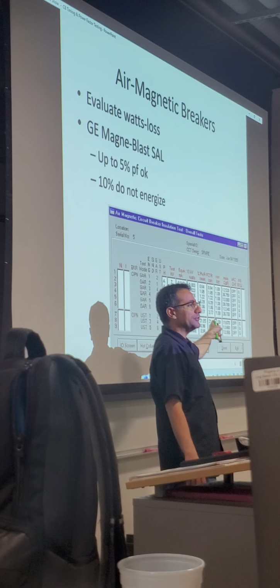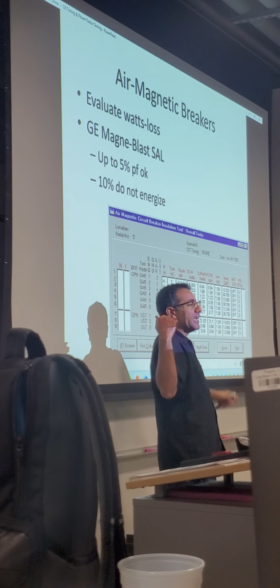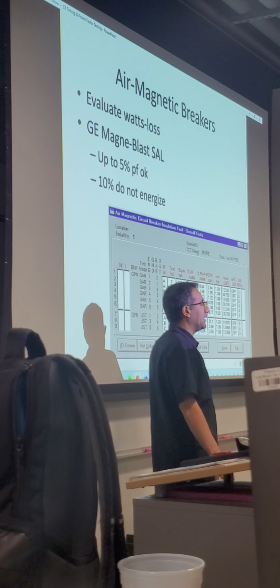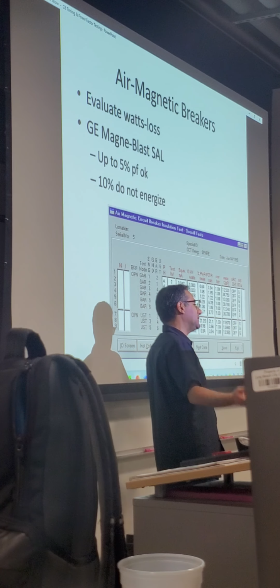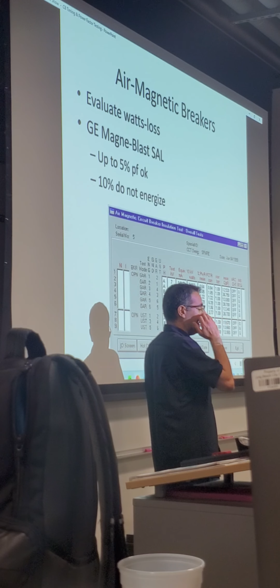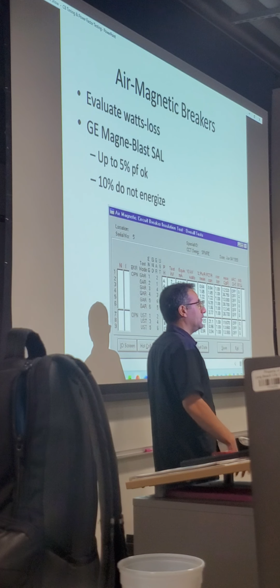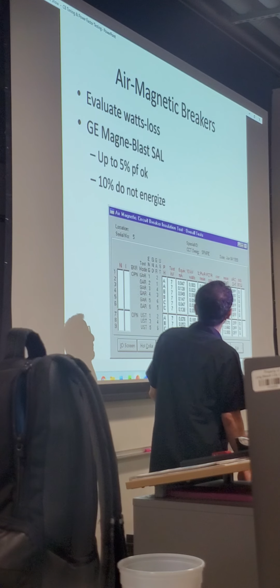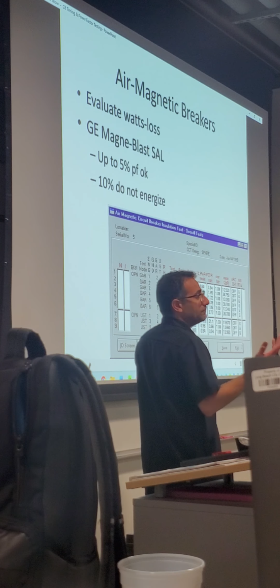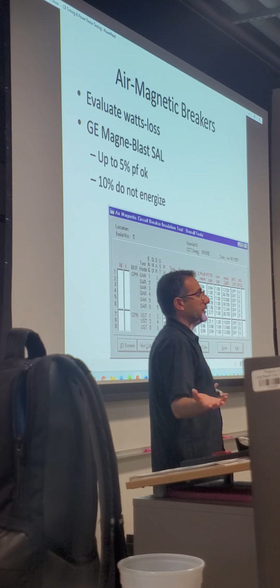Are these numbers good or not good? Look at the manufacturer literatures and publications. If you cannot find it, compare it with the sister units, or look at the previous test data. Look at the trend. It's getting worse. You have to flag it. But there is no rule of thumb here.